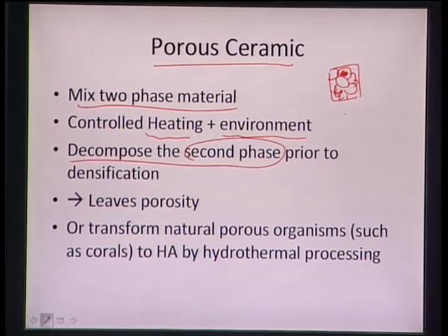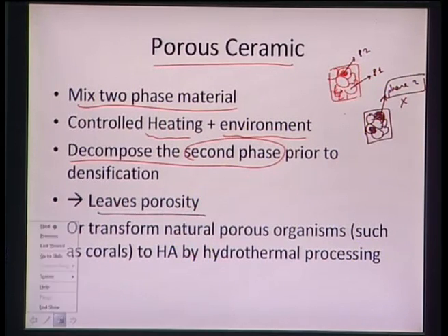So what we are doing, it's more like this, that we take a particular component, and in the second case we basically burn off the second phase. So we remain with only first phase material, whereas the second phase material has been decomposed. So it will leave certain porosity in its place. So this was phase 2, which is now basically burned off. So this was phase 2, this is phase 1, and now phase 2 has been removed, or decomposed. So we have an overall composite with certain porosity in it. So that is what leaves the porosity behind.